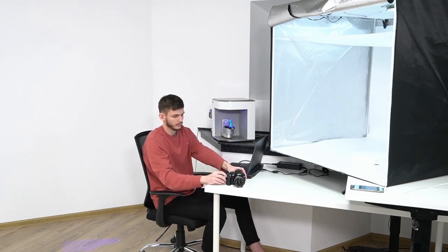All right, with this project, just like with the previous one, once all the data is captured, we'll go through the exact same number of steps of processing, right? We'll erase unnecessary surfaces from the scans. We'll align our raw scans. We will position the frames very precisely against each other using global registration.